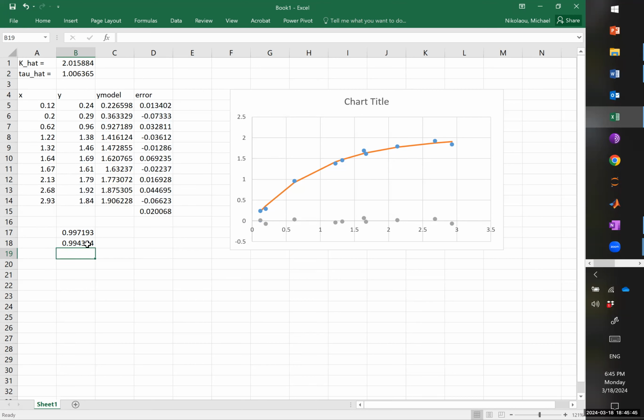Models, especially nonlinear models, are good for interpolation. I don't know what is happening outside. I suspect, based on fundamentals, that this model will predict also further down in time because there is fundamental structure in the model. It comes from this differential equation, and maybe the differential equation is second or even third order, or there are higher dynamics, but eventually, if it's a stable system, it will go to a steady state. I can trust this outside this range based on additional knowledge, not based on the R square.